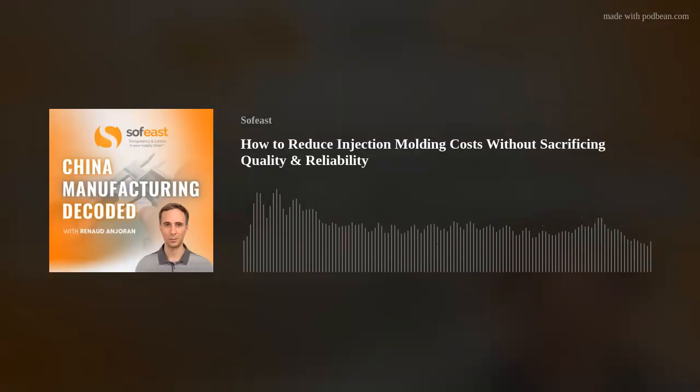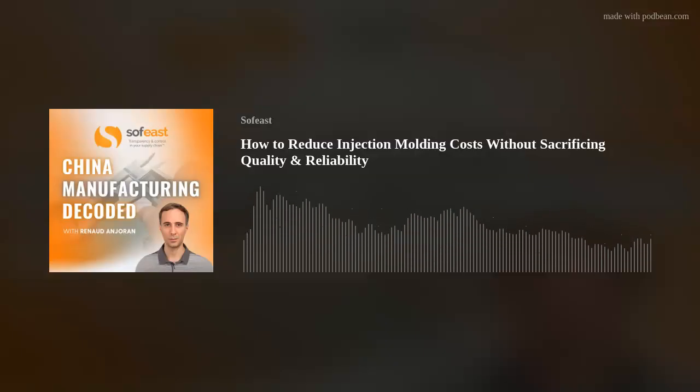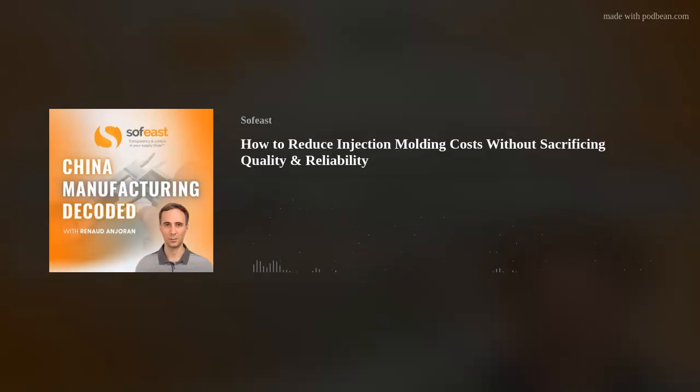Another one is all about regrinds. We've all talked about regrinds. Regrind is where you take your cold runner system where your part is attached to your sprue and runner. The sprue and runner is clipped off and wasted. Well, it's not generally thrown away. What we do is regrind that and potentially use that on non-critical components, i.e., go back to our battery cover. That'd be perfectly okay. But